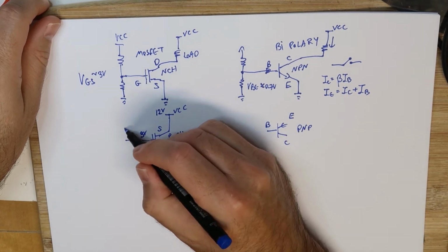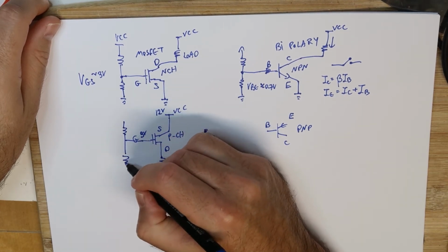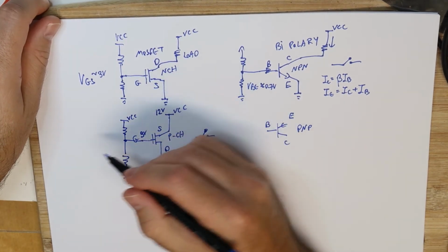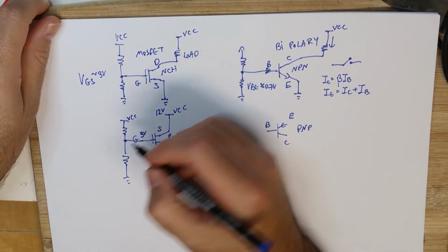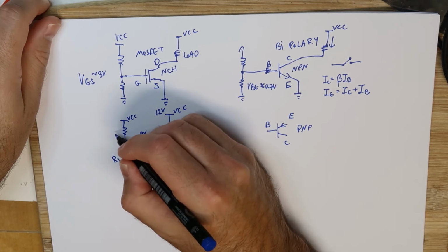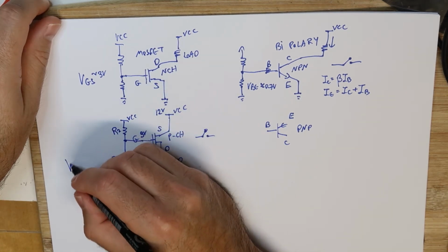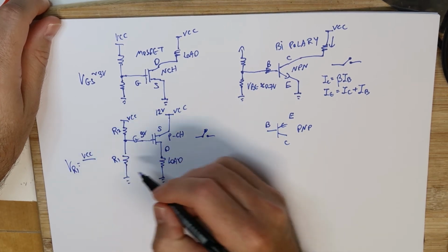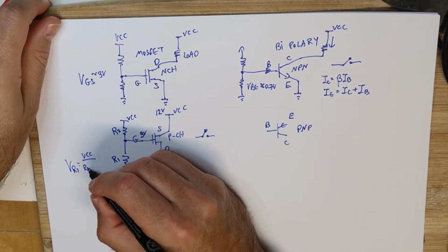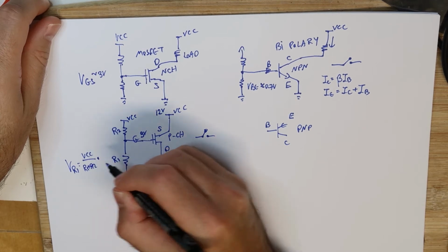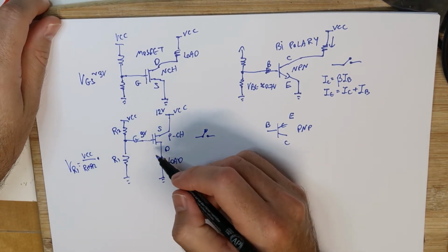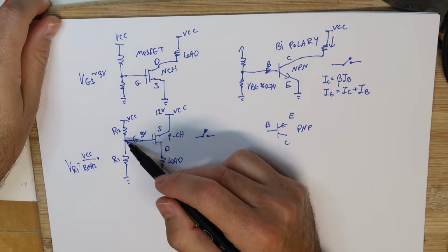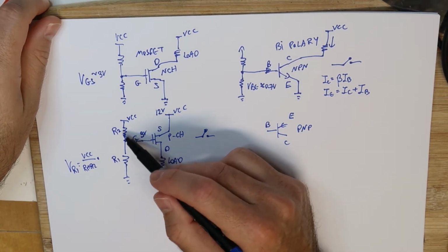So again, here we can put a divider of 2 resistors, and we can calculate it very easily. Let's do one example. This is R1 and this is R2, so VR1 is equal, of course, to VCC divided by the 2 resistors R1 plus R2, and this is all multiplied with, in this case we want to calculate the voltage here.